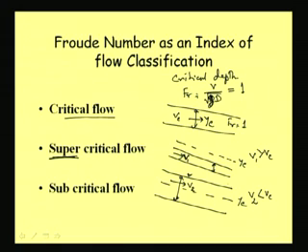And of course, in terms of depth, if I write it as Y1 and this as Y2, then we can say Y1 is less than Yc, the critical depth, and here Y2 is greater than Yc. But many a time it gets confused which one is sub, because sub generally refers to a lower value.